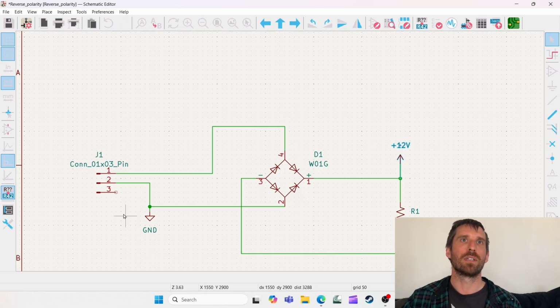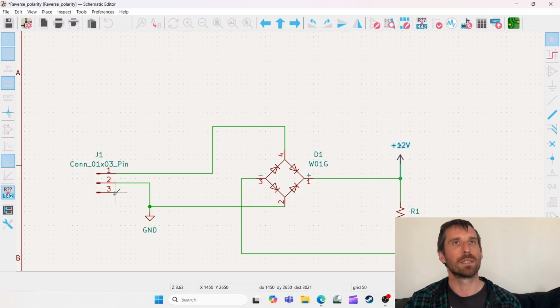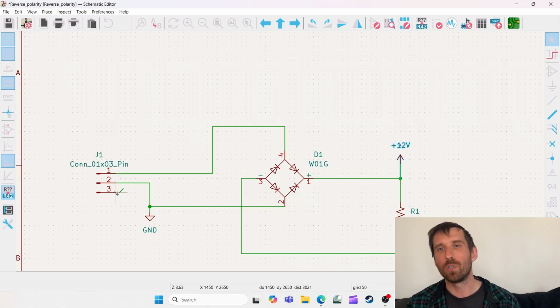So another thing I want to mention, since we're here about keyed connectors. Sometimes you're not in control of the connector itself. Sometimes you are in control of the pinout. So I put 3 here because if you just did the 2, power and ground, and you reverse it, well, there's your reverse polarity. But say 3 here, I reverse this, well, there's nothing here. So the circuit won't work. So depending on how you do your pinout, you could protect against reverse polarity. So something to think about.